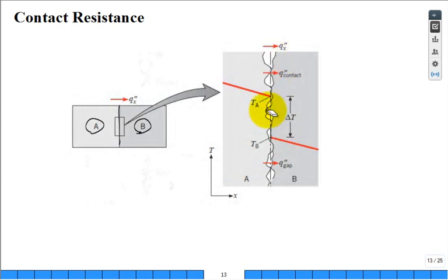Well, what's filling those gaps is very important to the heat transfer, because as you have a temperature flow, at steady state heat transfer, it's as if there's a big temperature drop right across the gap due to this resistance because of the contact. So if it's filled with air, air has a low thermal conductivity. If it's filled with some sort of grease, like a liquid, then that's a much higher thermal conductivity.